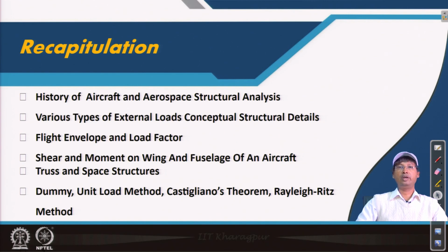From transformation we saw that we can find a coordinate system with a set of normal stresses, sigma 1, sigma 2, sigma 3, known as principal stresses, acting on planes where there is no shear stress. We also came across shear stress at any plane, good examples like octahedral stress, and the stress ellipsoid. Those are the things we learned in the last week.